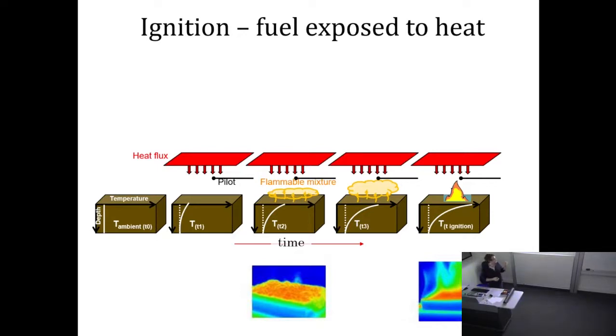Turbulent because if you are in a fire, you are looking for something that is seriously threatening, not just a little candle. "Call the firefighters, there's a little candle in my room." No, these are big rooms. And also because fire very quickly makes the buoyancy make the flow turbulent. Not because of the Reynolds number per se, but actually the instabilities that happen because of buoyancy.